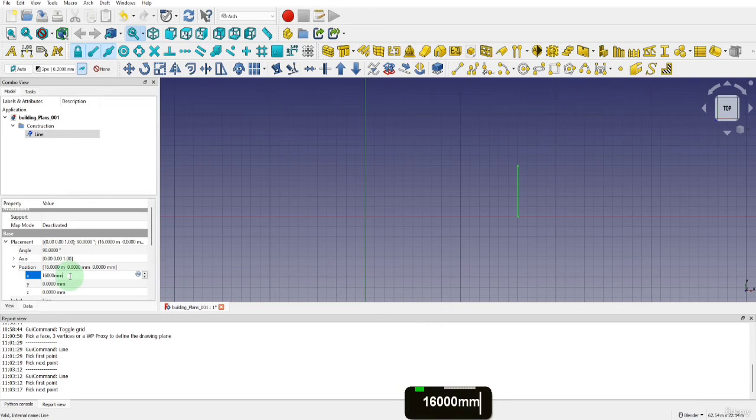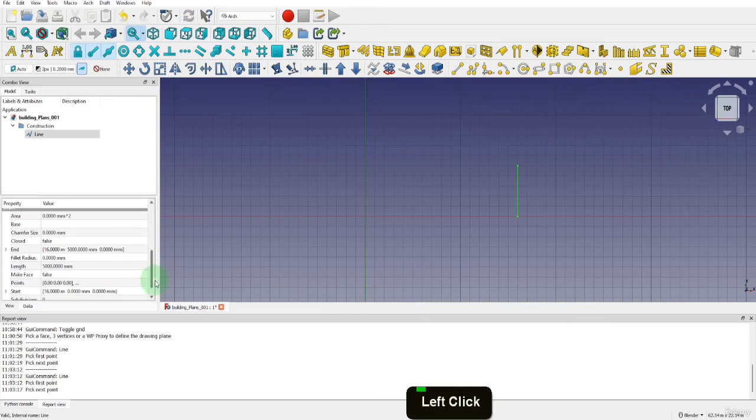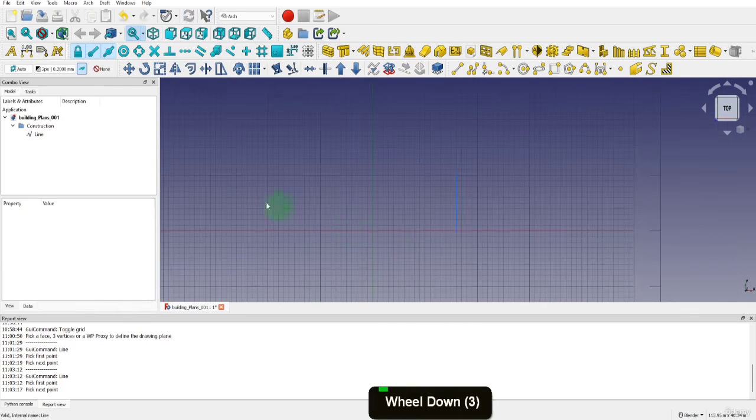You can specify the unit of metric in FreeCAD if necessary. So input mm for millimeters or m for meters. So this would be 16 meters or 16,000 millimeters. Finally, in the length field, we can input 1000 mm. Now we have an endpoint here to snap onto.